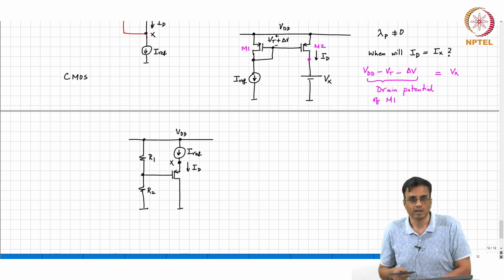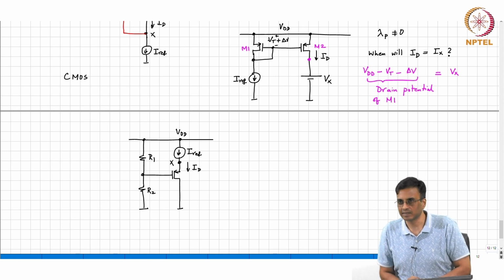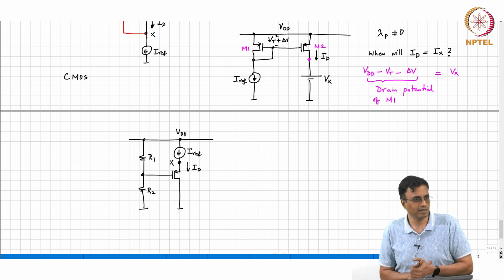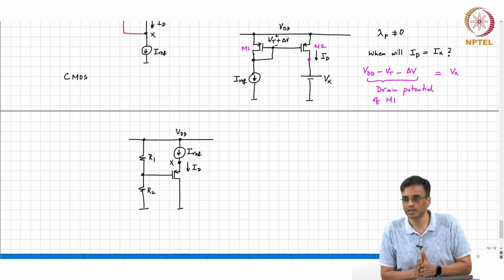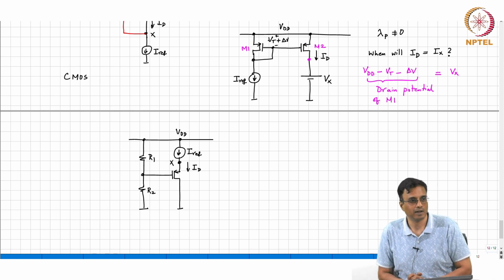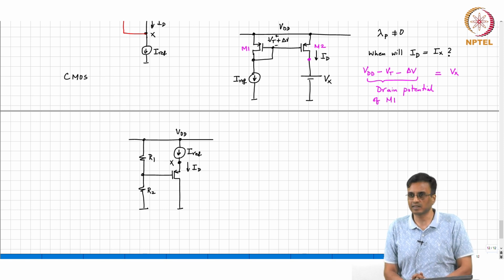The question is, if you are making an IC, then a current source is okay because it will need a transistor, right? And on an IC, transistors are free. But if you are working with a discrete board where transistors are expensive, what did we do in the NMOS case? That's what I am saying. Throw all the keywords that you have learned: inductor, capacitor, voltage source, current control, current source. Yes, Ralph. You put a large resistor, right?